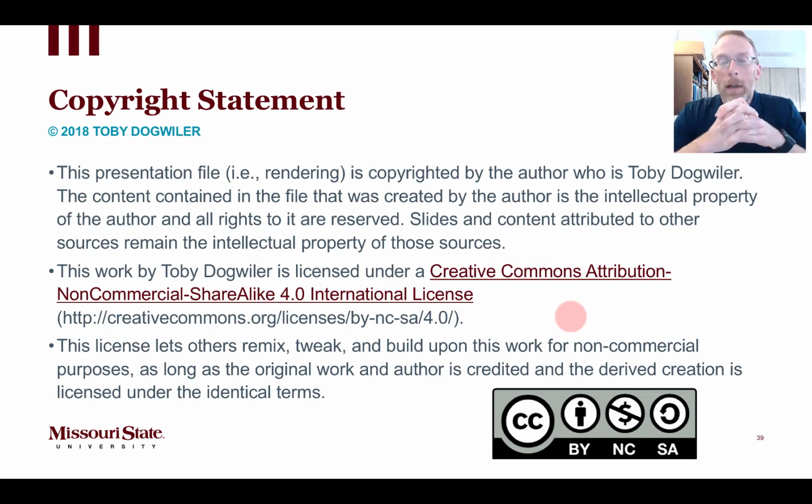All right, that wraps up the lectures for the groundwater module, and I hope now you have a better understanding of what groundwater is, what different types of aquifers exist, the relationship of those aquifers to the surface, either confined or unconfined, some concepts like unsaturated and saturated zone, or vadose zone and phreatic zone, and some of the ways that aquifers can be contaminated, and some of the ways that we can actually use aquifers to store and clean up water, as in that last slide.